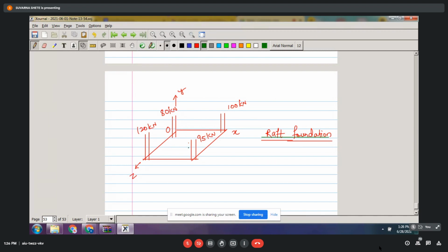So in this case, can you tell me along which axis all your weights are? Y axis. It is along Y because your vertical is Y in this case. So we can directly skip summation Fx. We need not go for summation Fz, because no force is along the x direction or z direction. All the forces are along y. So I can write simply summation Fy will be nothing but Ry, which is nothing but R. Right? Yes, ma'am. Okay.